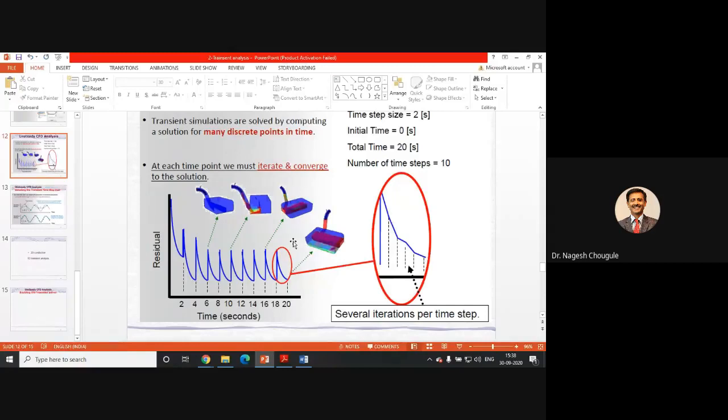A coarser mesh is required at the center, but at the boundaries where the solid-fluid interface is there, we can make use of non-uniform meshing. And we can even select higher order elements, going for polynomial elements instead of linear.